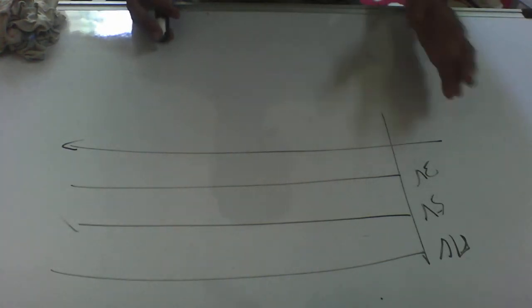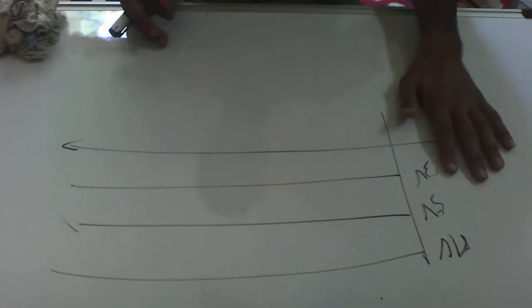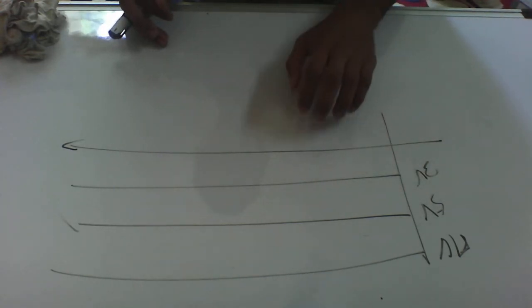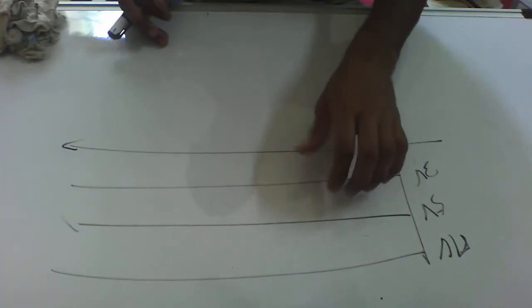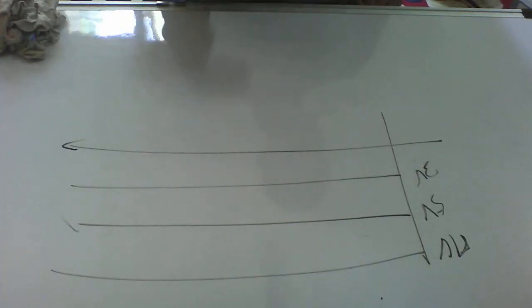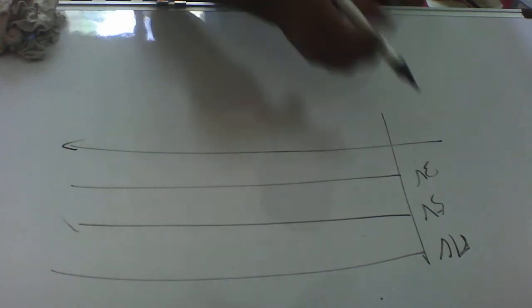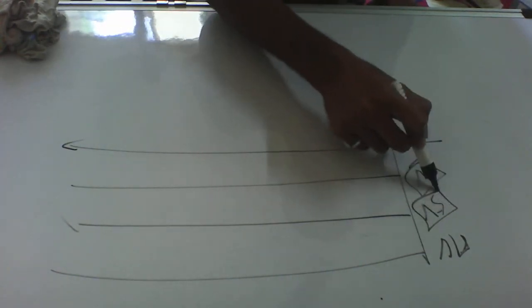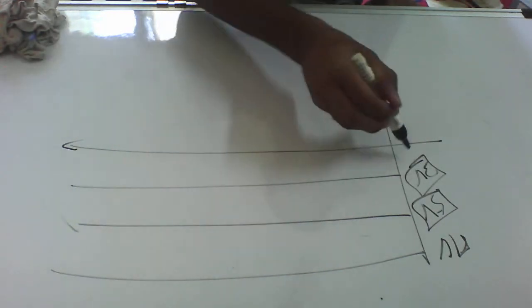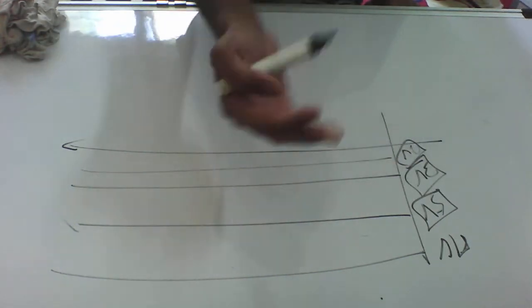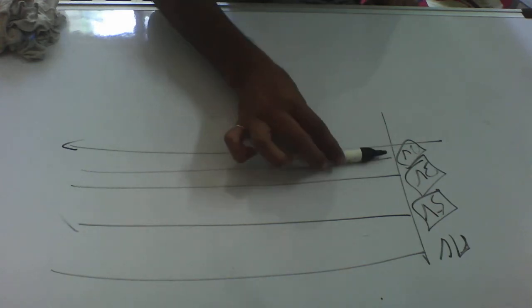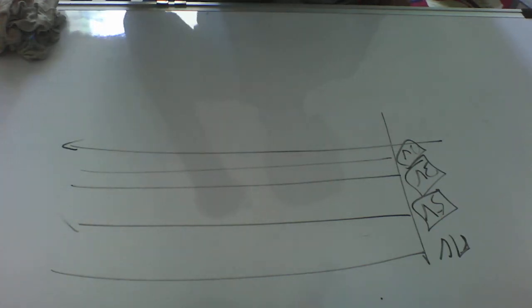So in order to get the specified magnitude, a voltage shifter circuit is used. A voltage shifter means a voltage converter. Basically it converts 3 volt to 5 volt, that is stepping up, or 3 volt to 2 volt, stepping down. So the level of the voltage is converted by a voltage converter.